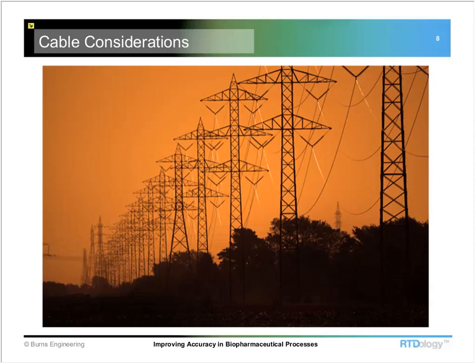But when we're trying to move beyond that plus or minus half a degree C accuracy range, you really need to look for a manufacturer that publishes a whole bunch of other performance characteristics, and we're going to look at some of those later. But there are other things in addition to the interchangeability and the drift. There's temperature cycling, hysteresis, vibration resistance, and those are just a few of the things that you need to concern yourself with when you're calculating an error budget for a particular measurement point.